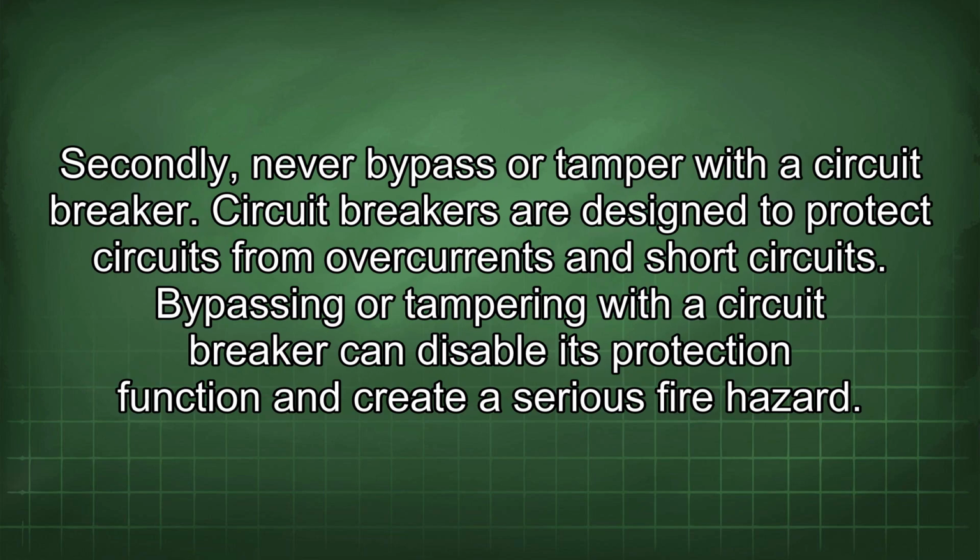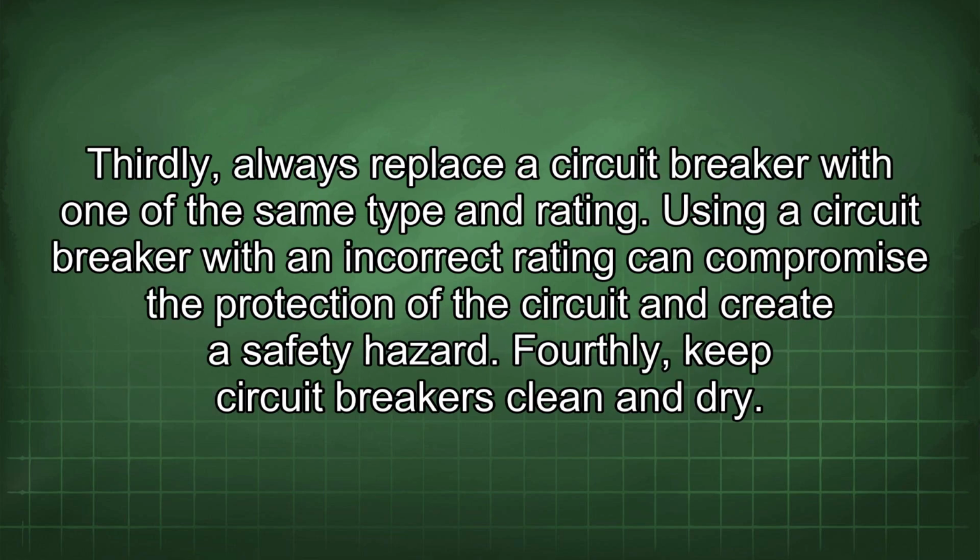Secondly, never bypass or tamper with the circuit breaker. Circuit breakers are designed to protect circuits from overcurrents and short circuits. Bypassing or tampering with a circuit breaker can disable its protection function and create a serious fire hazard. Thirdly, always replace a circuit breaker with one of the same type and rating. Using a circuit breaker with an incorrect rating can compromise the protection of the circuit and create a safety hazard.